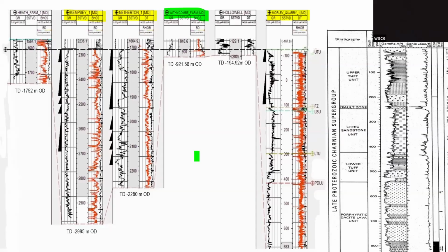You drill your borehole, you drop what's called a sonde down, like a metal sensor on a cable, into the borehole and then pull it back up slowly, and that measures the physical characteristics of the rocks around the borehole. From that procedure you get this continuous log of borehole physical properties. In this case, they're looking at the gamma ray, which measures the radioactivity, and the sonic log and the density log on the right-hand side, which measure the sonic velocity and so on.